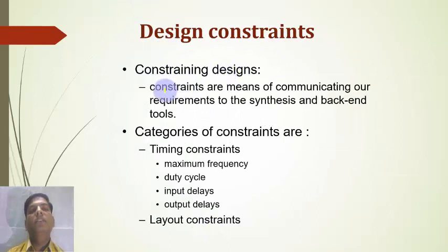Design constraints. Constraining designs: constraints are the means of communicating our requirements to the synthesis and backend tools. Categories of constraints are timing constraints and layout constraints. In timing constraints, there are maximum frequency, duty cycle, input delays and output delays.